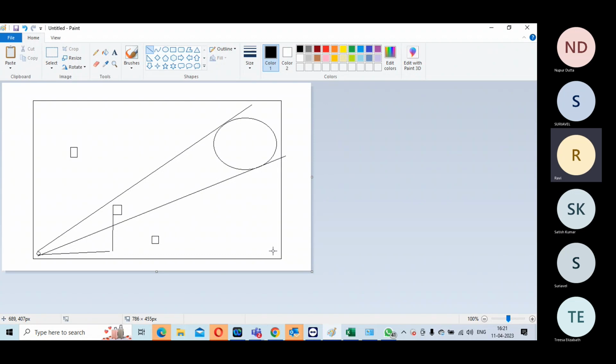If these two clocks are not related and they are getting some skew paths, you can insert a lockup latch and inform the tool. But once you are inserting a lockup latch, you will fail the LEC formal verification. You can give rules to fix that, not a problem. You get that point? Yes, sir.